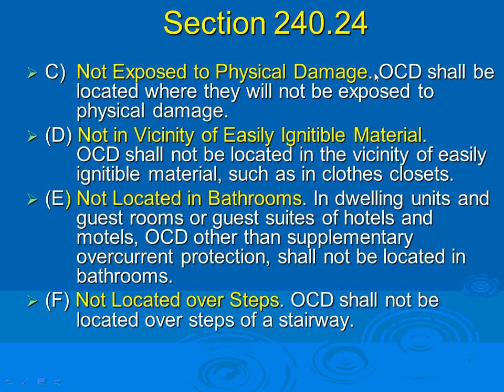Not exposed to physical damage. You don't want your fuse or circuit breaker to be exposed to physical damage. You don't want to put it in a Class 1 Div 1 location, obviously, unless it's rated for a Class 1 Div 1 location. Closed closet, you don't stick a fuse or a circuit breaker in a closed closet. That's ignitable material. You don't want to do that one. Not located in bathrooms.